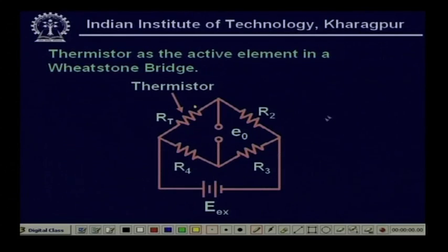This unbalanced voltage I can feed to a V2F converter, and then to a frequency measuring circuit, a counter or frequency measuring circuit.